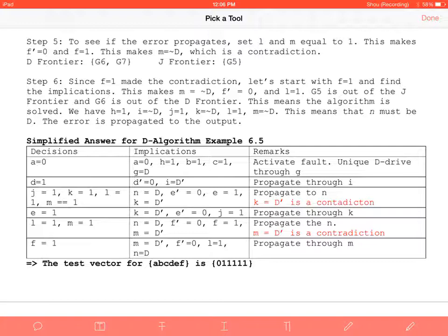I don't know if any of you will still be around, but I will, in 2 years, be offering an undergrad/graduate course in testing and fault tolerance. So this goes much deeper at that level. For CMOS, this is sufficient to understand that once you synthesize the circuit, you need to figure out some sort of testing. There's troubleshooting if you're trying to figure out a small circuit. If you get a slightly larger circuit, that can become problematic. Before you use automatic test pattern generation, you can use your propagation justify algorithm, or you can use your D algorithm if you know there's fan out.